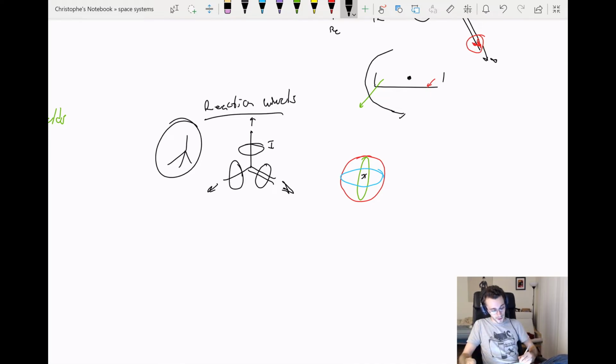So if this reaction wheel is saturated, I can use components of the other three to speed up a certain degree and then have this one slow down a certain degree, and I will maintain my angular velocity. And then I can re-speed up that slowed down reaction wheel to get even more of a boost in that direction.